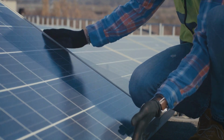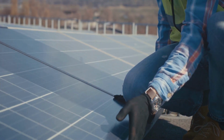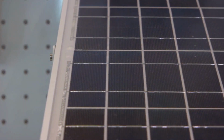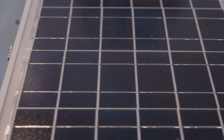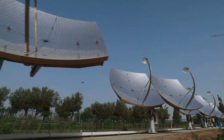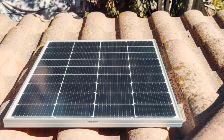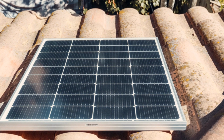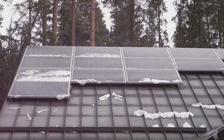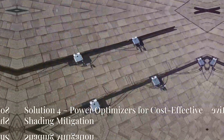For those who want to handle shading on a panel-by-panel basis, microinverters are an excellent solution. Microinverters, like the Enphase IQ7 series, convert power at the panel itself. So even if one panel is shaded, the others continue producing at full capacity. Microinverters are ideal for complex shading situations, especially if you have trees, chimneys, or nearby buildings casting partial shade on your array.